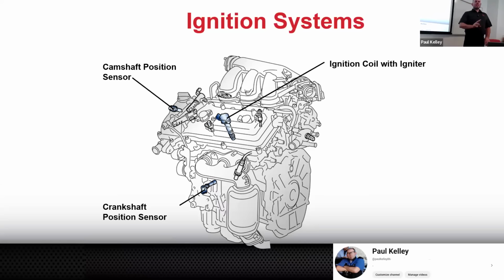Cool. Now, and that's fairly easy, right? If the misfire follows the spark plug, it's the spark plug. Are we going to do one spark plug? Probably not. Probably going to do the set of 6 in this V6. If it was the coil and it follows the coil, what's the car need?